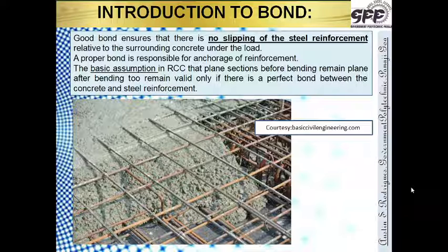The bar has been put over there as reinforcement, but whenever we are putting the bars on the formwork, there is grease which is applied. Now if this grease comes on the bar, even by mistake because of walking of the persons, or maybe while painting the thing has been done wrongly, or maybe the bars were kept down on the formwork and the bars have been lifted, so the bars have got coated with grease or oil. So in that case slipping can occur, bond will not be there. If there is no bond, we have understood that the composite action could be affected.